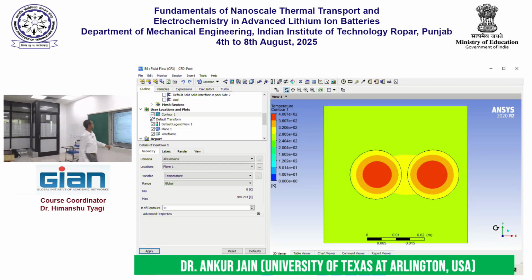This cell is slightly, not much, slightly cooler than the other one, simply because this is slightly closer to the cooling boundary. Not a big difference. So if your battery engineer asks you, should I place it this far or this far from the cooling boundary, your answer is yeah, doesn't matter, do whatever you want, right? It's not a major effect. Clearly your battery engineer is also juggling 5 other constraints, so he or she will be happy to hear you say it doesn't matter.